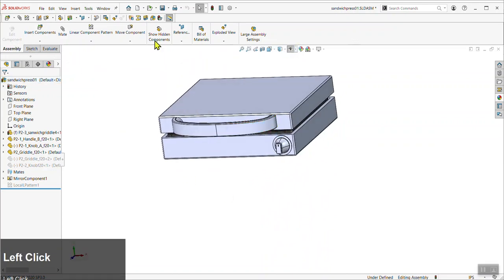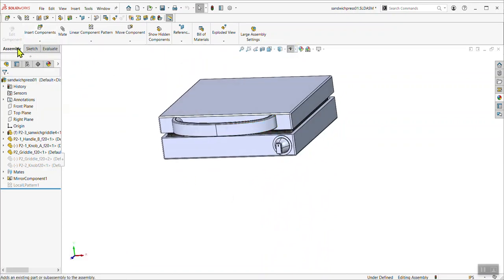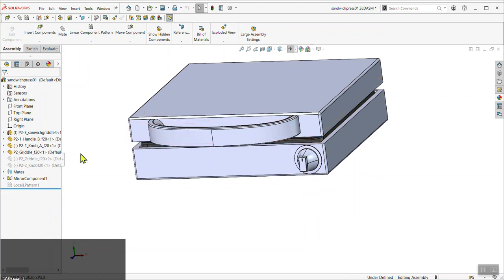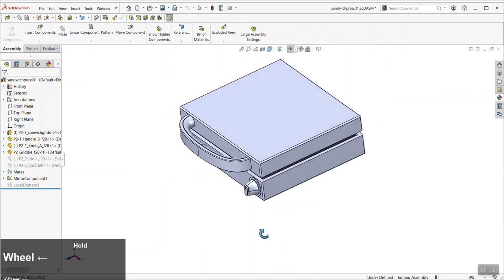As I mentioned, I wanted to call attention. You can see now at the top, the feature tab is now missing. Again, that's a good thing. The only features you want in here are assembly features. If I start seeing fillets or extrudes in this tree, that is not good file practice. It leads to errors, and so points will be lost on the project. So there you have it. That's assemblies.